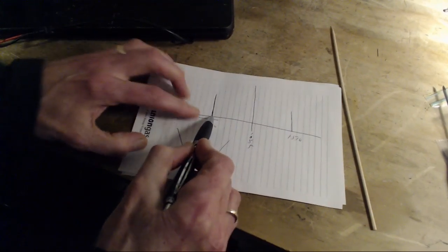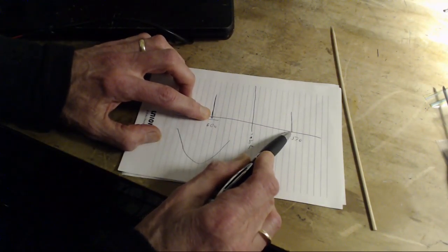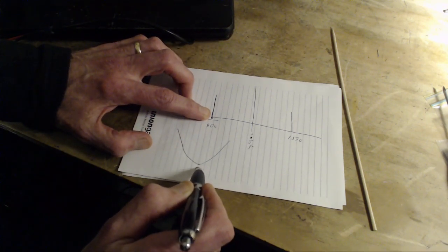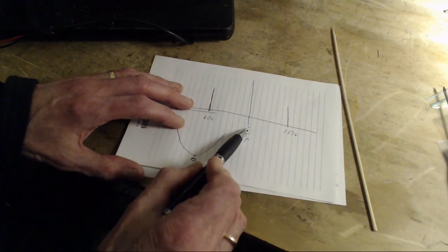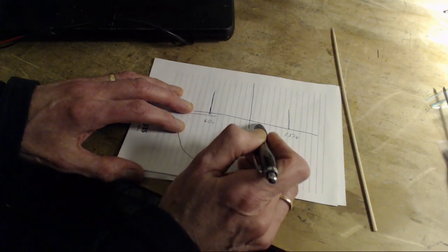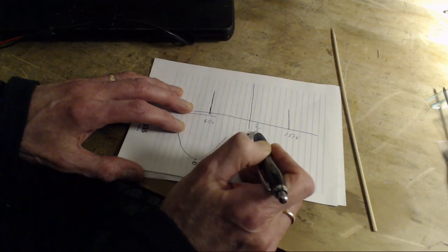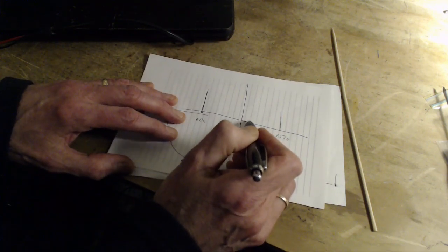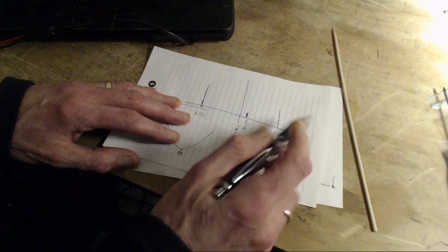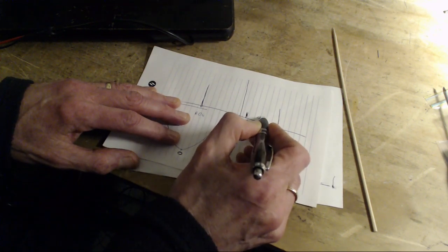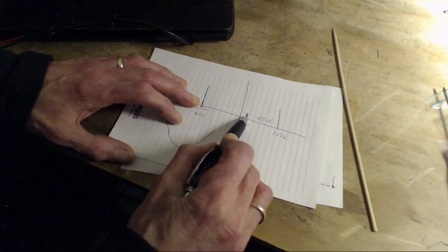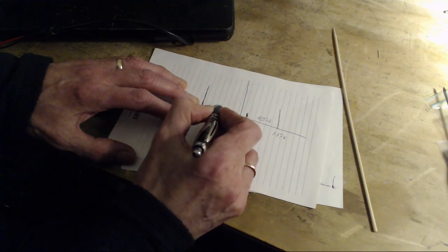Then when you tune in the 600, even though the 1510 is coming through, you probably won't hear anything because you're at the lowest point of this pitch, which is 0 cycles actually. Now let's say you tune the local oscillator 1000 hertz that way. So now it's at 1056. So what's happened now, it's here. The distance between here and this signal is now not 455, it's 454, and the distance from here to here is 456.